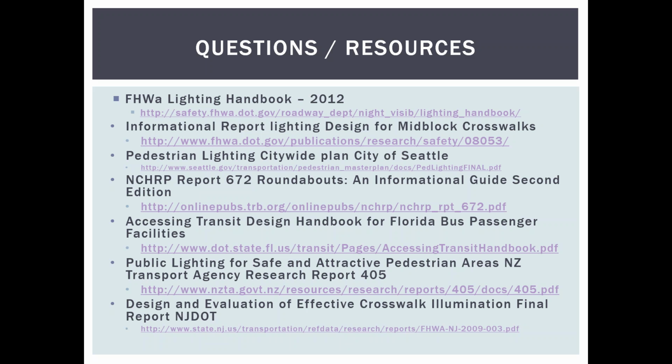And the biggest concern is during the heat of the day in the desert areas, if a photocell is not working, causing your light to become on when it shouldn't be coming on during the hotter part of the day, that's when you're really killing your LED lamp.